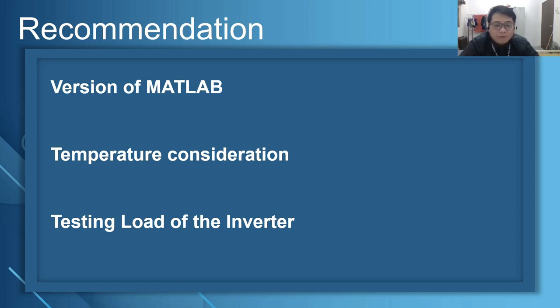In the process of obtaining the transfer and output characteristic graphs of both MOSFETs, the latest version of Matlab shows a problem, which is that it will put everything you have extracted from the simulation scope into one folder in the workspace. And the name of the data declared by Matlab itself is always a changing variable. And this causes the problem that the output characteristic graph is unable to be achieved when you set different gate voltages. So my recommendation is using an older version of Matlab. My recommended version is the 2018b version.